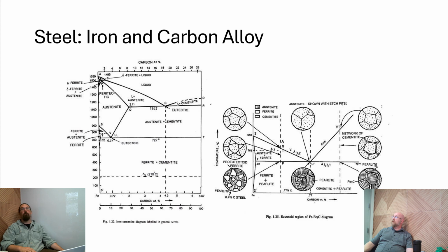So if you're in higher temperature applications and you want that dimensional stability, for instance on a tool surface, that's why you prefer a cast iron table for a bandsaw or for a machine tool on a ways. It's because it's dimensionally stable. So again, neutral things. Application drives whether or not something is a desirable or an undesirable characteristic.